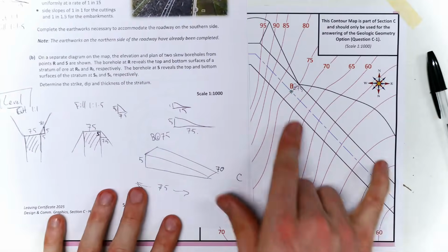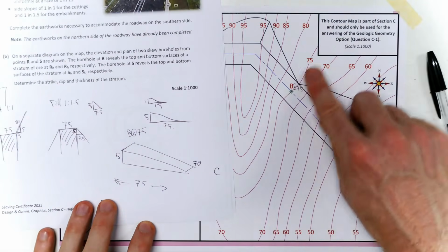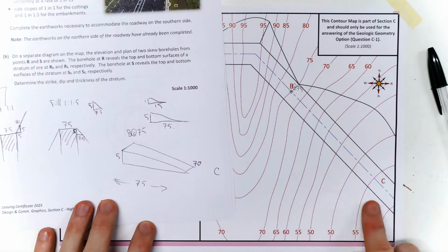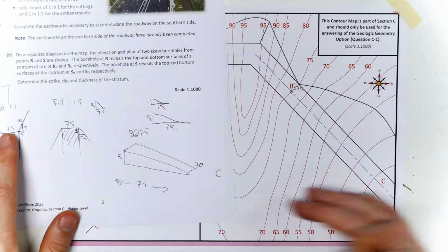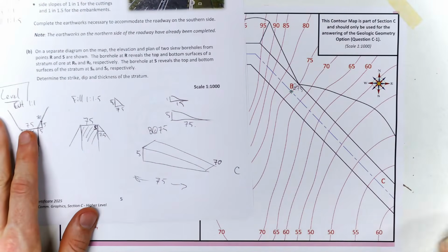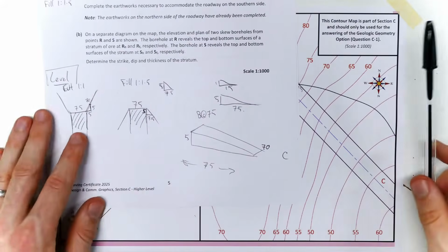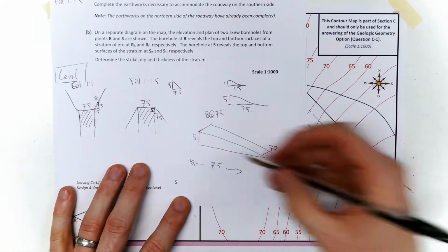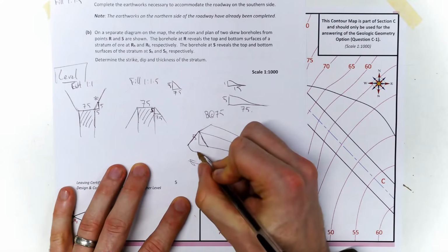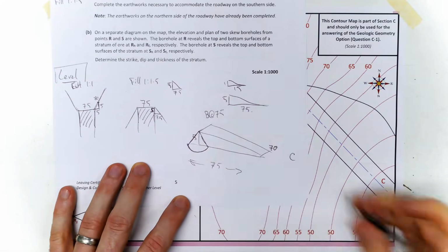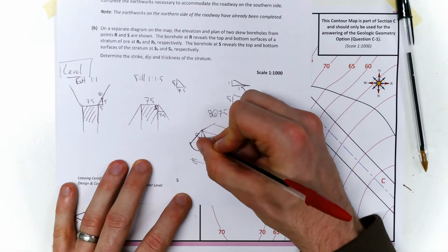And then if I'm looking here at this section, the contours are at 75 and 70, 60, down along. So I'm actually going to be doing a fill. Okay, I'll be filling up there because all those are going to be under the level of the road. So I'm doing a fill. Here's my cone, my semicone. Okay, the height of that cone is 5. I'll just highlight that, so it's 5.